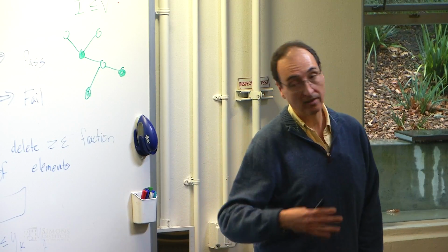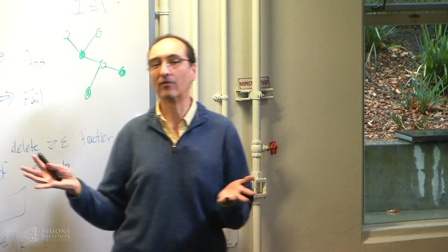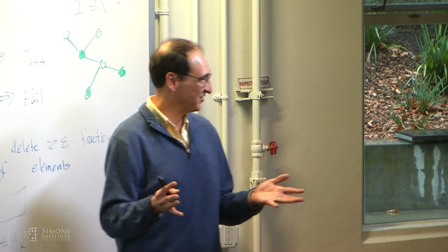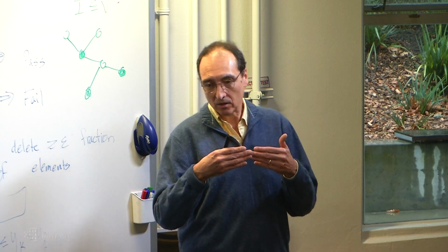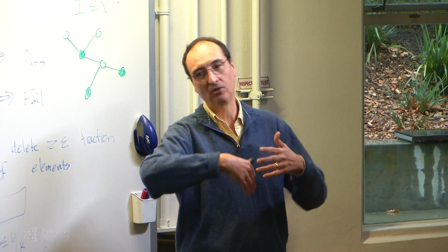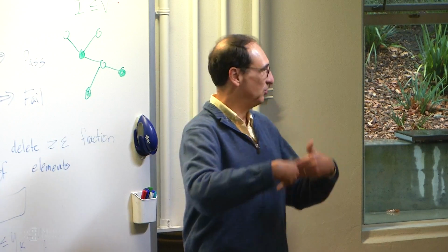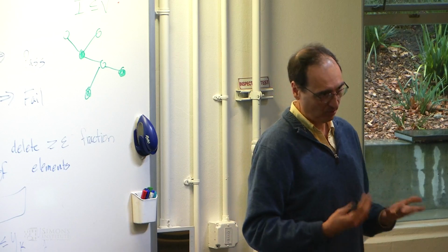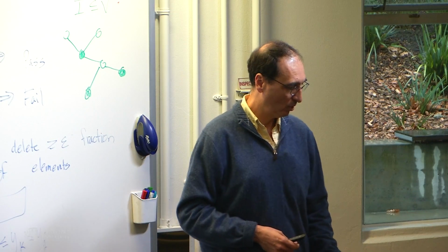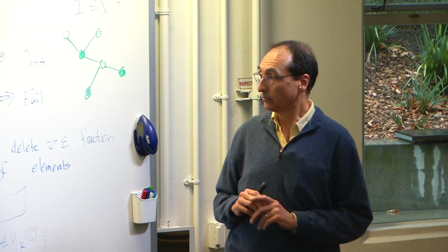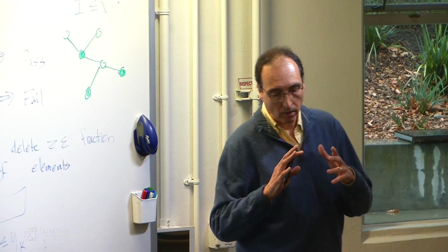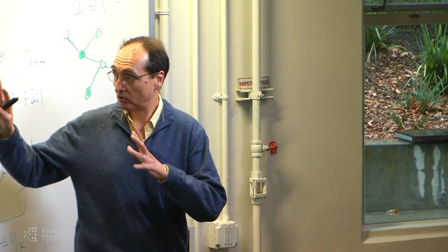So that's what's being done, and this is what more or less every autonomous car is doing, some version of this. You might do the trajectory calculation on a graph, you might do it with some sort of convex optimization, everybody's got their own tricks, but you're just redoing that calculation over and over again and doing receding horizon control. Okay, so that is sort of the trajectory generation.